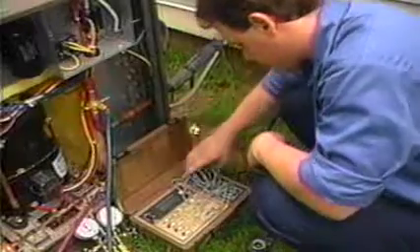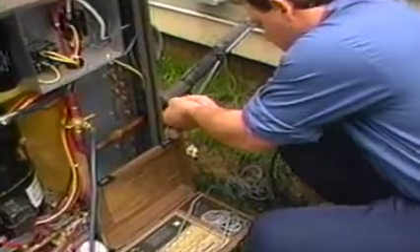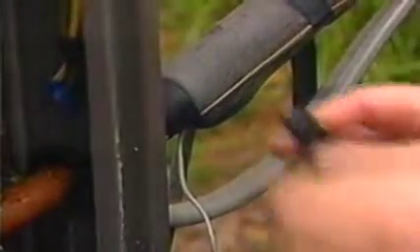When the evaporator supply air temperature needs to be obtained, a temperature test may be used. The supply air temperature will normally give a dry bulb reading about 20 degrees Fahrenheit lower than the return air temperature. This is known as the dry bulb temperature drop across the evaporator coil. A temperature lead can also be used in conjunction with the suction pressure to determine superheat. Convert suction pressure to refrigerant boiling temperature. This boiling temperature can then be subtracted from the suction line temperature to determine the superheat.